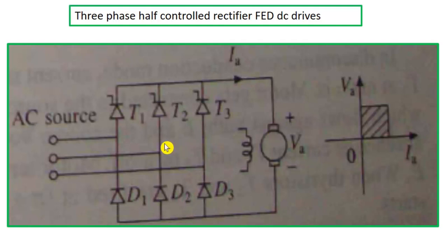So in brief we have discussed, today, thyristor fed single phase half controlled, single phase fully controlled, 3-phase half controlled and 3-phase fully controlled rectifiers, and the output voltage of those rectifiers is fed to a DC motor, maybe separately excited or series motor. And one traditional circuit of voltage control using an uncontrolled circuit we have seen, using different tappings of the secondary winding of the transformer. There also we can control the DC output voltage, but that is not the best way.